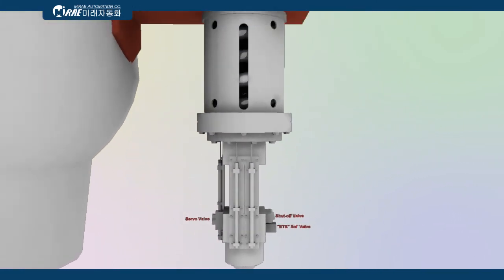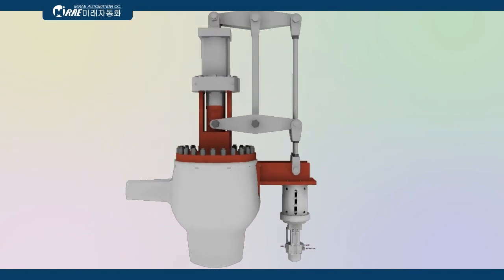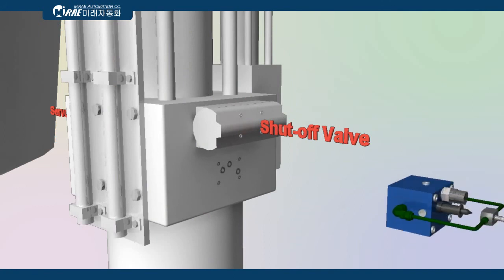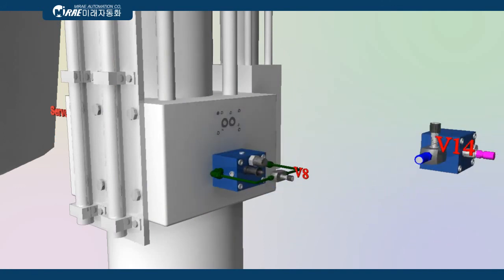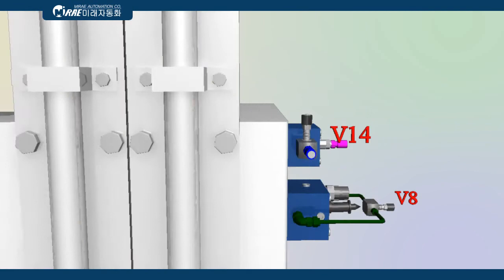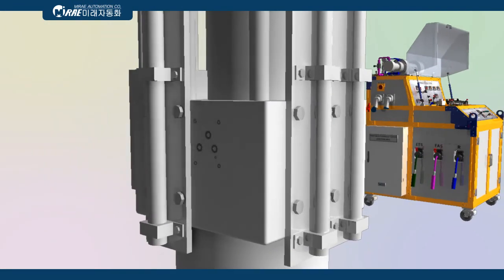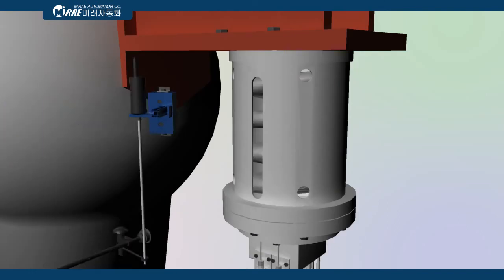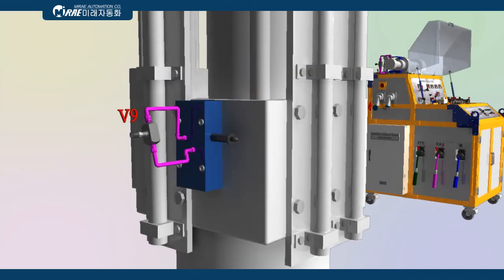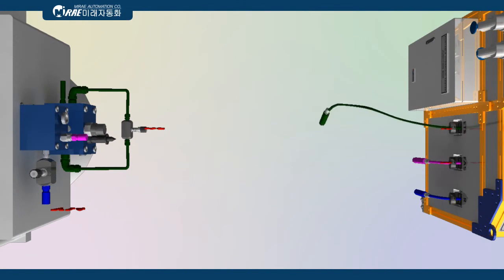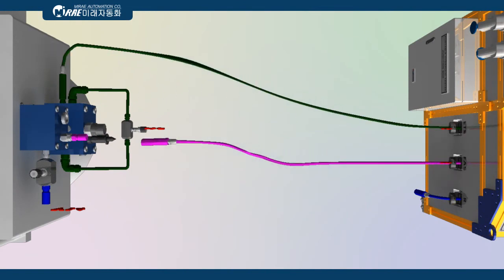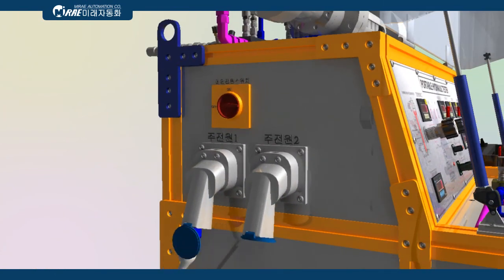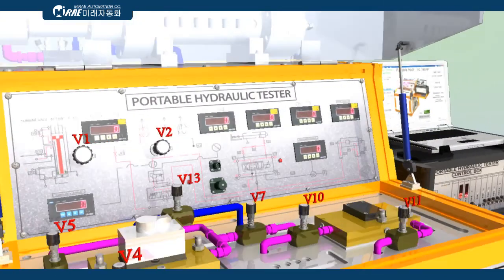The test steps of turbine valve actuator tester for performance diagnosis are to detach valves such as ETS solenoid valve, shut-off valve, and servo valve without detaching turbine valve actuator, displacement sensor, and to attach test blocks on the position of the valves, and then to supply hydraulic oil for the interior leakage test and dump seat leakage test of the turbine valve hydraulic actuators.